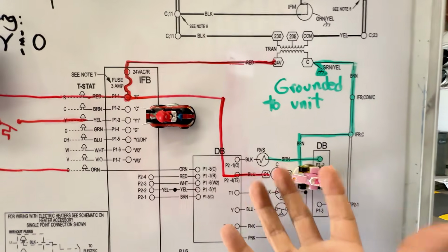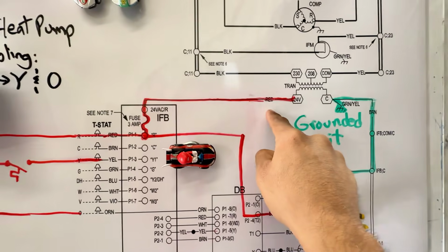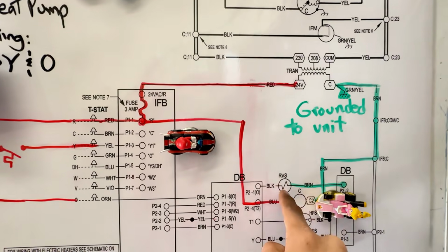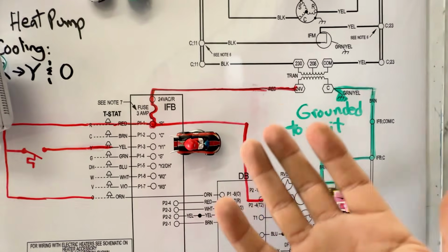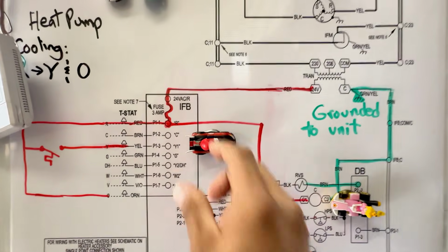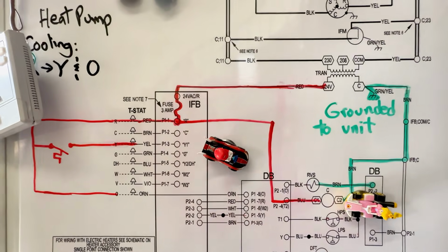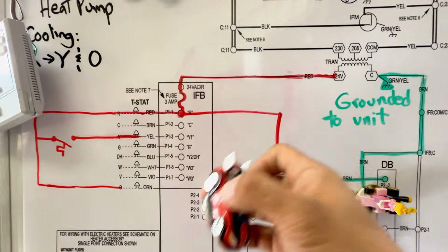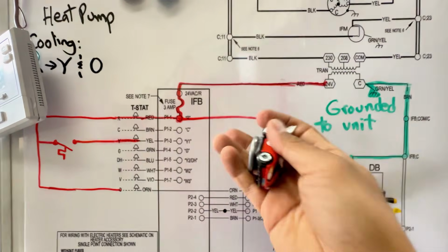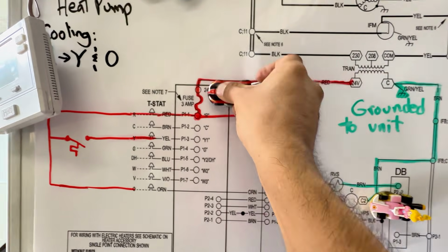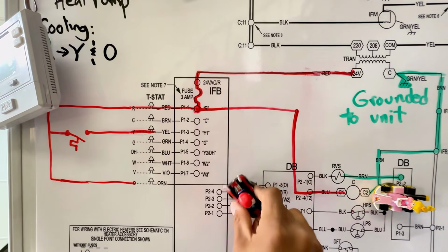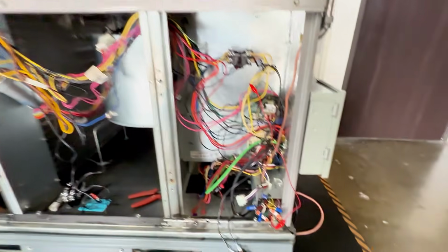making that load work. Mario, though, in the earlier clip, we had Mario go straight from the transformer, boom, to that load. That would work, but the system would be on all the time. So the way that we can do it right here is as follows. And this is another way, but just to show you, there's different ways of doing it, but this is not the right way. So Mario can do it this way, and on the thermostat, he can then take a detour and go to the load. Would that work? Sure, that would work. Not the right way, but it would work.